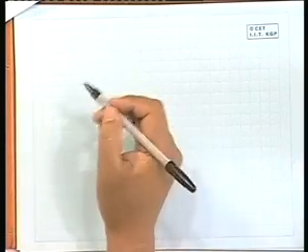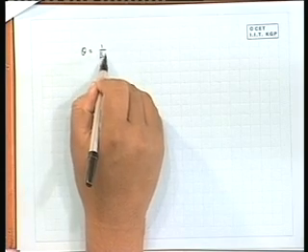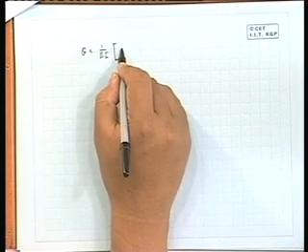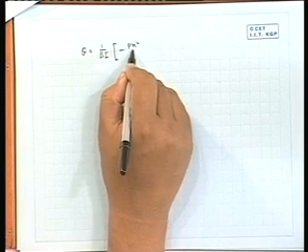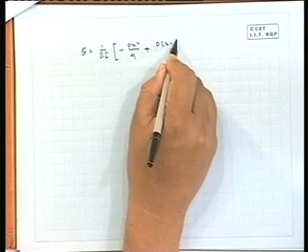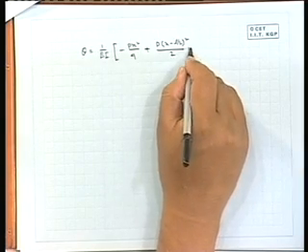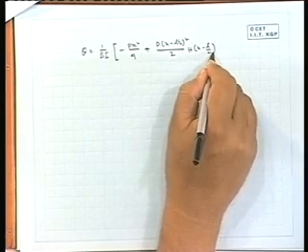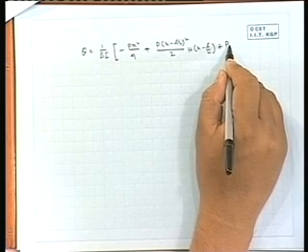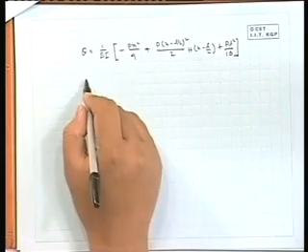So, we can write the slope theta as 1 by EI, that should be minus P x square divided by 4 plus P (x minus L by 2) square divided by 2, and C1 will be there, it will be PL square divided by 16.